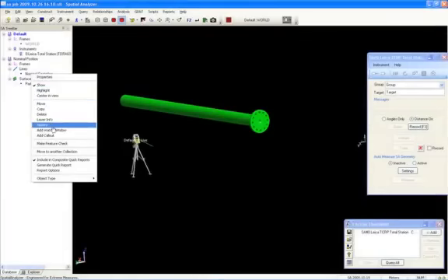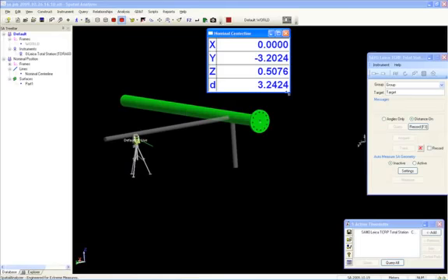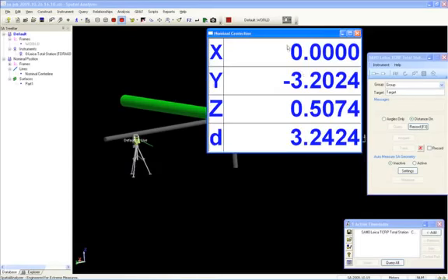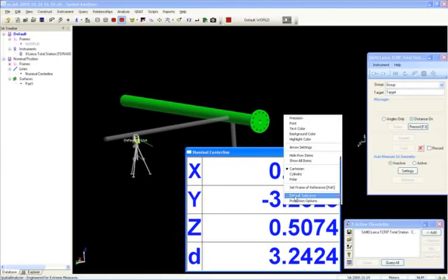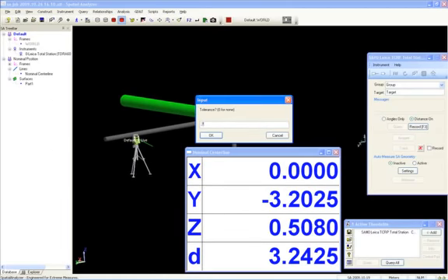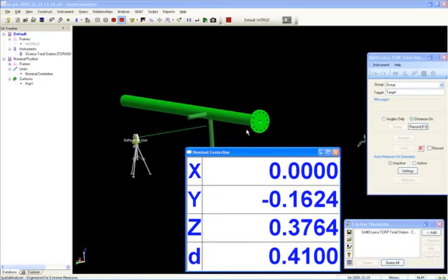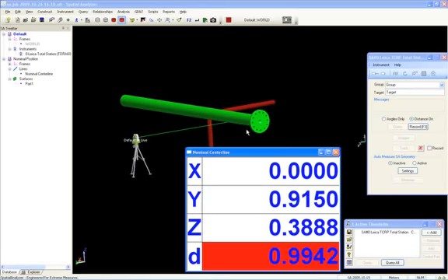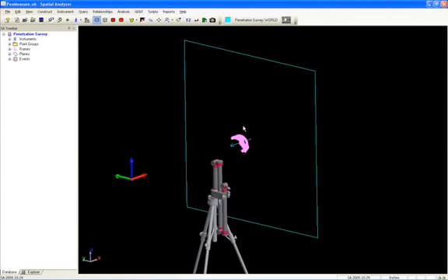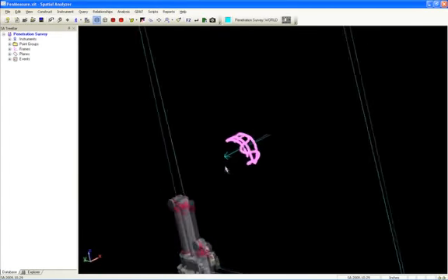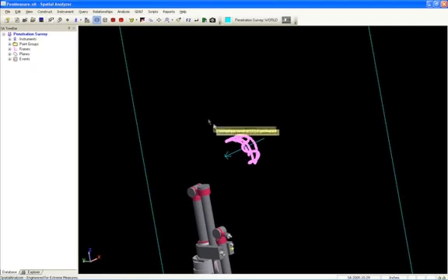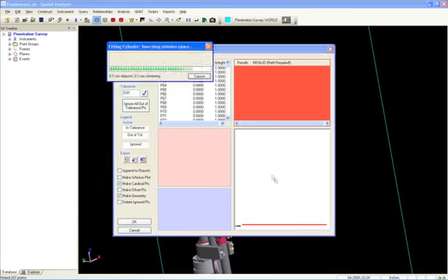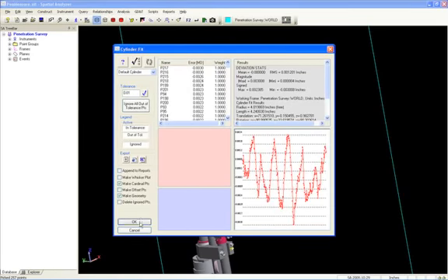Watch windows are live instrument updates which allow you to align objects in real time. They compare an instrument's target position to any point or object of your choice. The windows allow you to attach tolerances to help guide the measurement technician toward an acceptable tolerance range. In this example, we've measured a pipe penetration through a bulkhead with a portable CMM. In just a few steps, we can fit a cylinder to these points, then check the orientation of the penetration against the nominal bulkhead orientation.